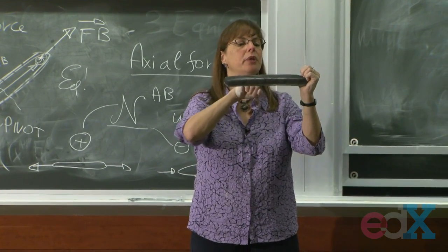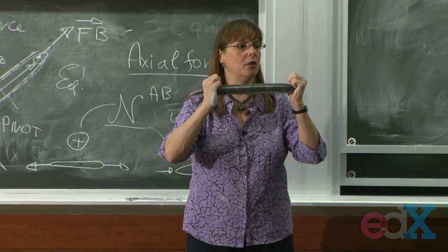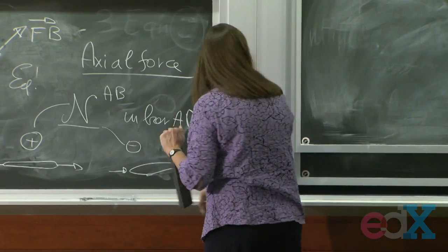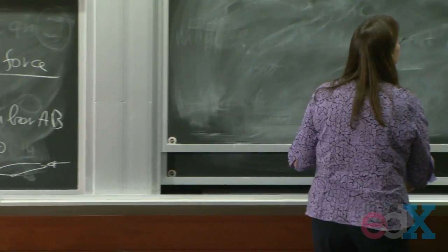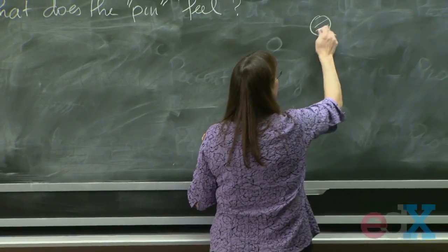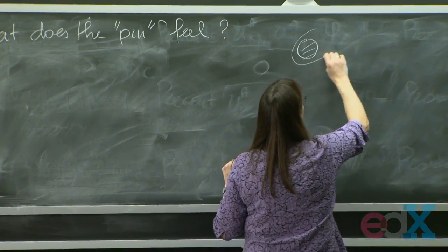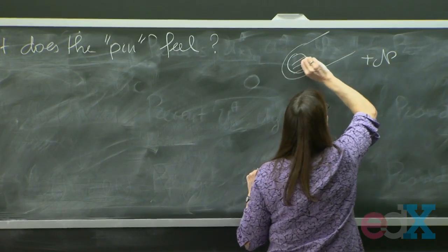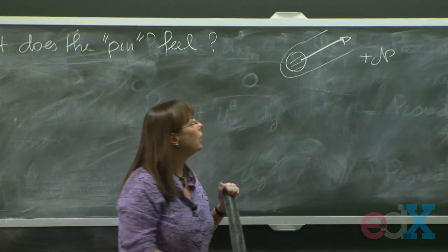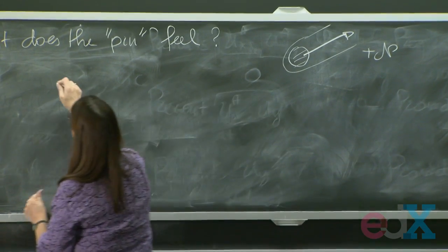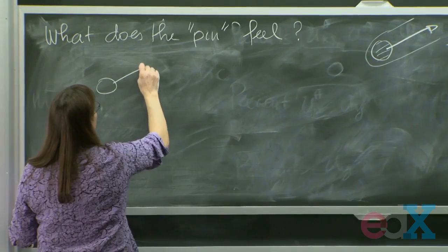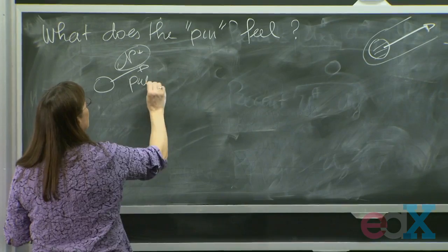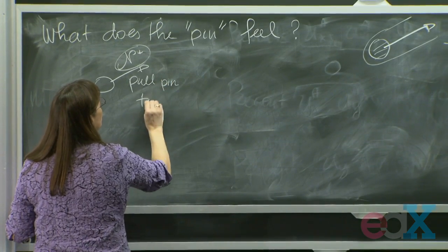Do they feel pulled into the bar, or do they feel pushed by the bar? They feel pulled. So if you have a pin attached to a bar, a positive axial force means that it pulls the pin towards the bar.